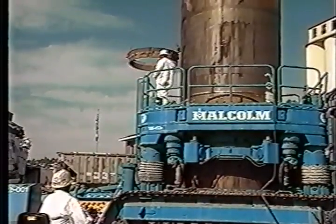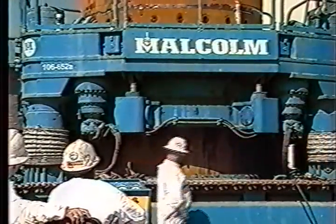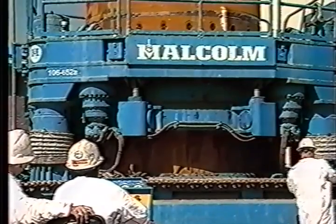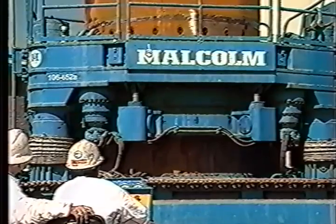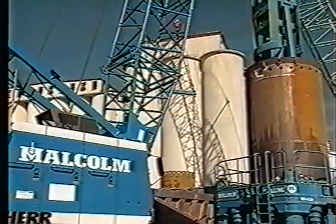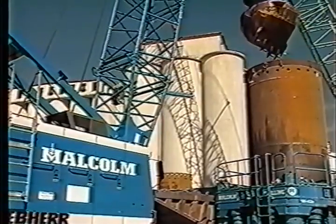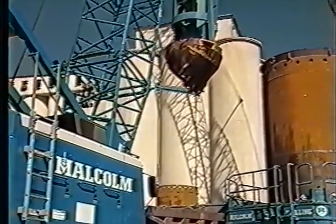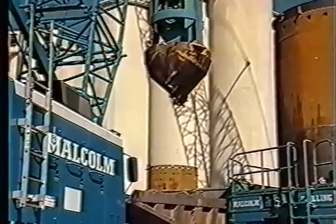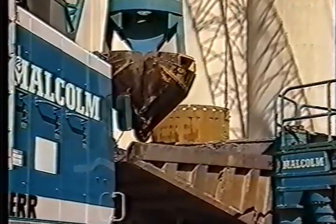The bridge support was designed with 2 drilled shaft supported abutments, with 4 6.5-foot drilled shafts at each abutment and 7 piers with 2 10-foot shafts at each pier. The geotechnical makeup of the site for the installation of the shafts was mainly loose to medium dense dark gray to black sand. The grabs clam out the dirt and muck, while the rotator continues to rotate, forcefully twisting the casing into the ground.